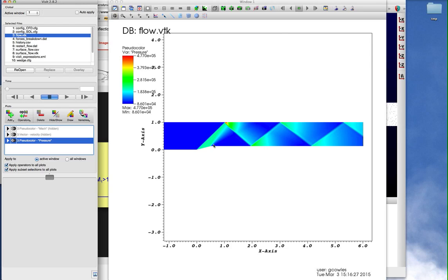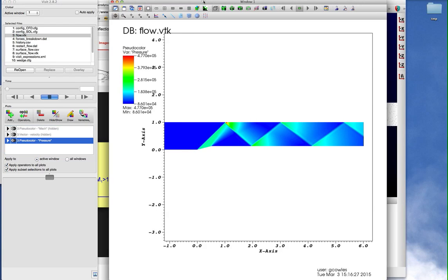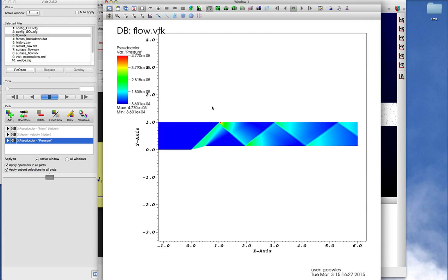and we have that other feature I mentioned, which is the Prandtl-Meyer fan. This expansion around this point right here. So that's what I want to say about that. It was just a quick little flow solution. It wasn't meant to be the highest-quality result, but to give you an idea of oblique shocks, and what can happen in the special case up here of a detached oblique shock and reflections in supersonic flow.